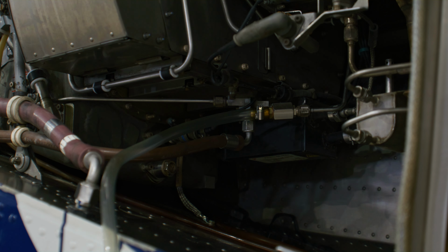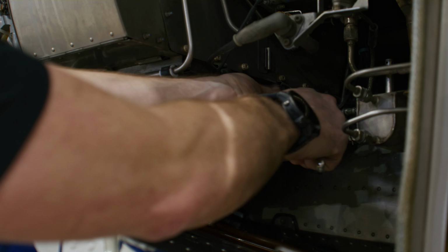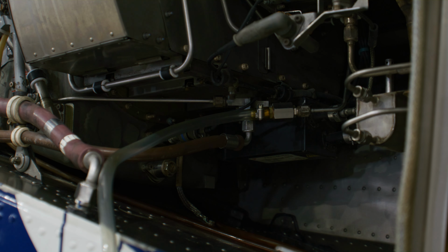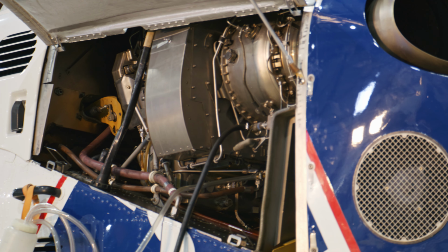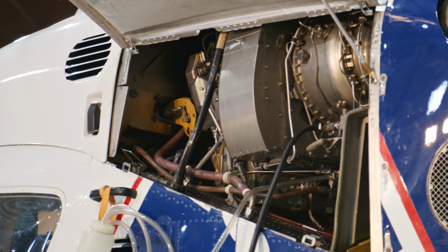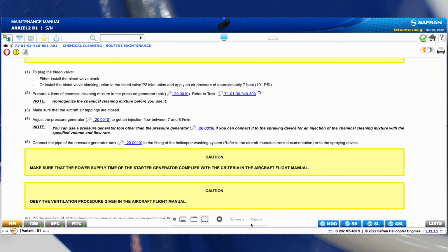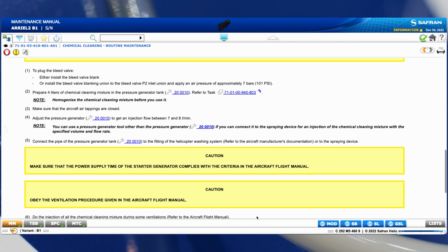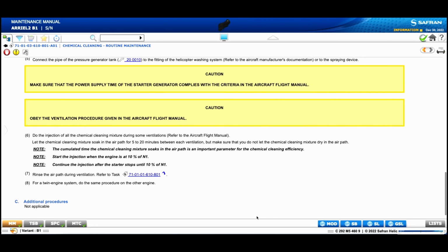With the drain valve open, cleaning liquid which has accumulated in the combustion chamber can move up through the main fuel injectors, through the injector drain pipe, and back to the drain collector, which returns to the fuel tank. Not a good situation. Disconnecting the drain line and capping the collector prevents any cleaning or rinsing liquid from reaching the fuel tank.